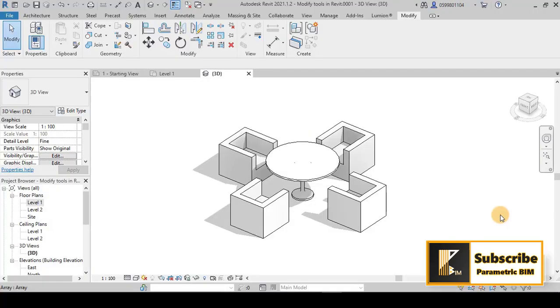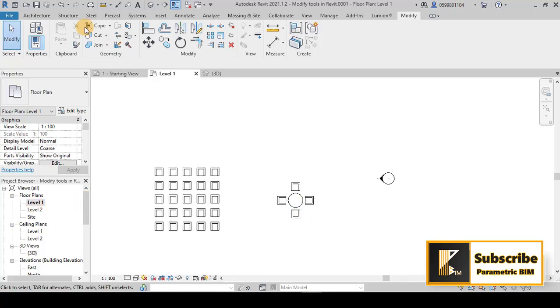For scaling objects in Revit, it may be done by using the scale tool in the modify tools. So not all the objects in Revit can be scaled, but most of them, such as lines or profiles, can be scaled, or if you import images in Revit. So I am here going to draw, for example, a wall.